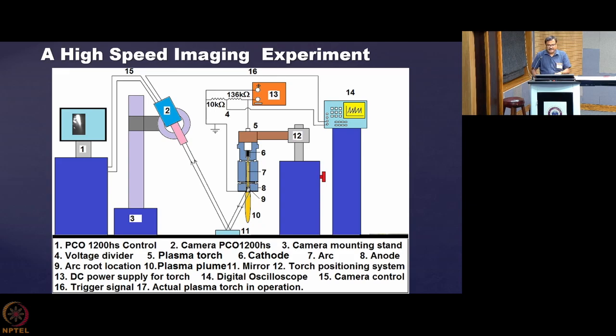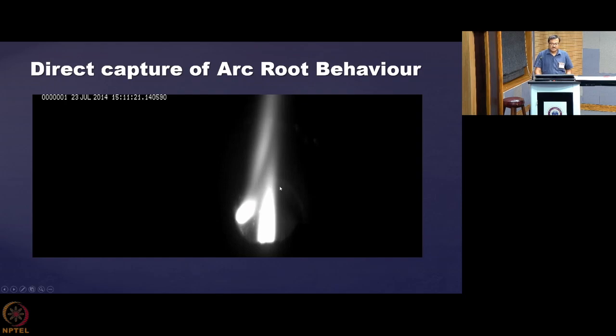So to find a proof of that, you can go for this kind of arrangement. Because of the very high temperature, you cannot directly look into this, so you can have its image over a metallic reflector, and then you can look at the reflector using some camera placed a distance away, so that the camera doesn't get affected by the thermal flux that is coming out from the torch. We will be discussing more on this in the tutorial.